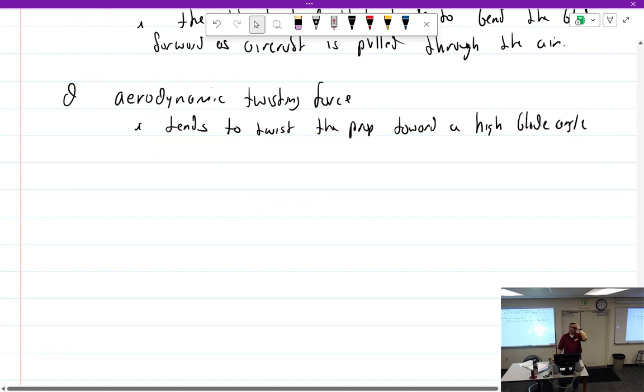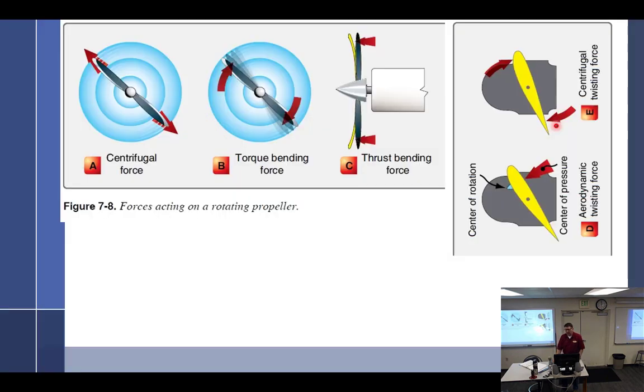So it's going to get confusing as we start talking about blades. High blade angle, low blade angle. So one thing I want you to get in your head right now, and this will make it easier, is that in a constant speed propeller, the blade rotates. I've got it right here. This blade moves back and forth, and it's like this. Not a great deal, because we already learned that 1 degree is like 60 RPM. So it's not a great deal. This is in my way, so I got to move that. I'm on mic stand. I was doing karaoke when you guys were around.